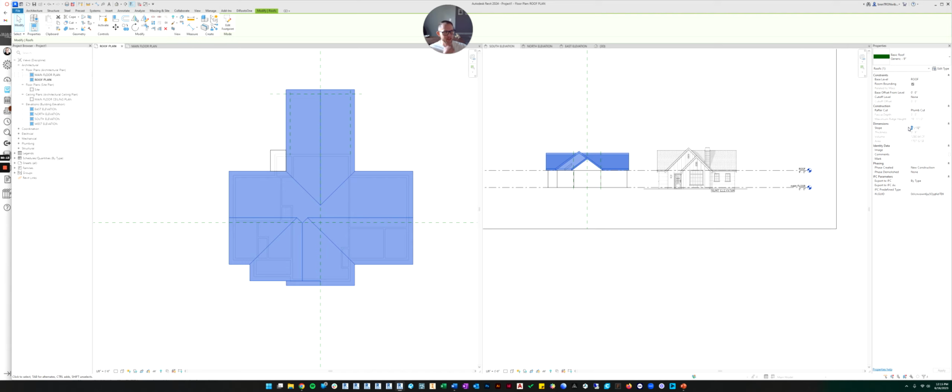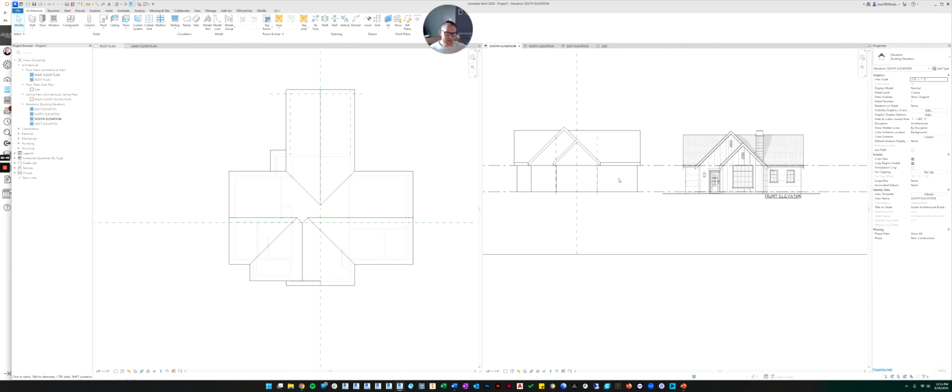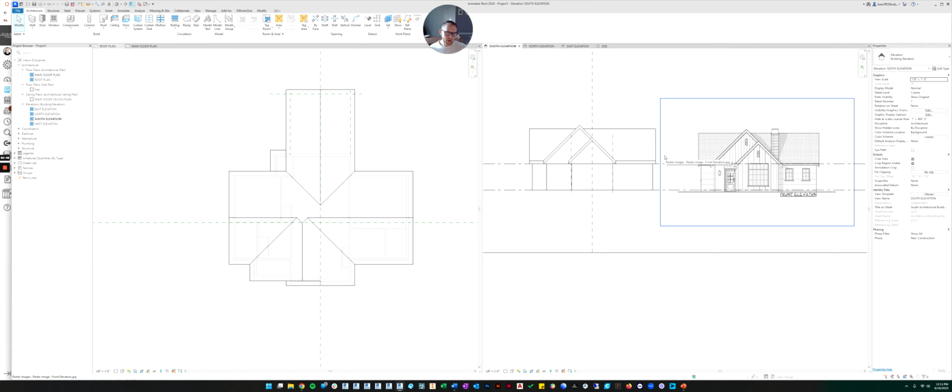Let's change the slope to something steeper. Instead of 9, let's do a 12-12. That means for every 12 inches it goes over, it will go up 12 inches. So this is showing the rise and the run. The rise goes up 12 inches, over 12 inches. When it was 9, it would go up 9 inches and then go over 12 inches. So if we do 12-12, you can see it got steeper. Maybe that was too steep because now it's a little bit higher, but I think it's actually okay the way we have it. I like the 12-12. It makes a nice 45-degree angle.